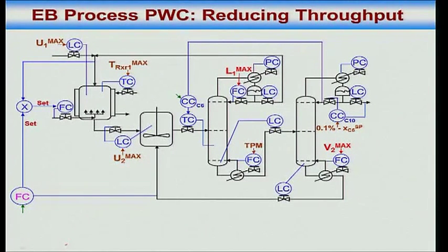If V2 is kept at V2 max, what that means is the boil up is large, therefore I am boiling it up. To not allow the diethyl benzene to leak up the top, I will have to reflux more. Yes or no? So I am unnecessarily recirculating things here in this way, and I am wasting steam.